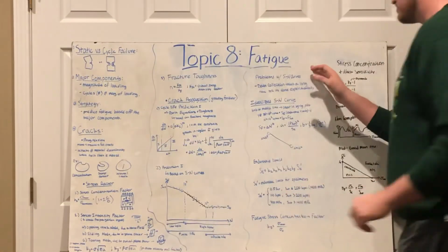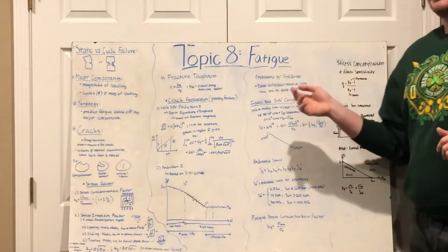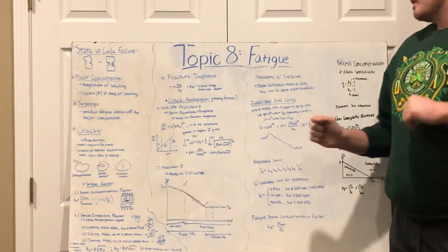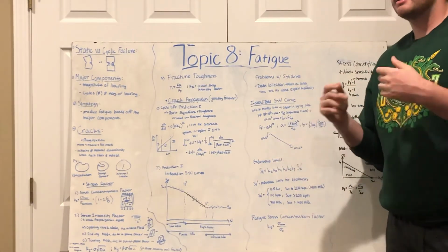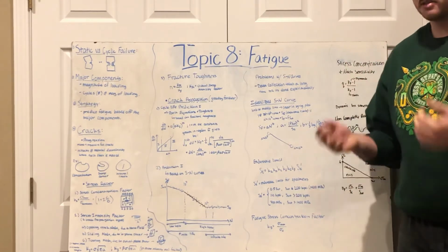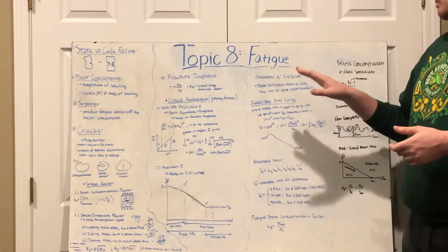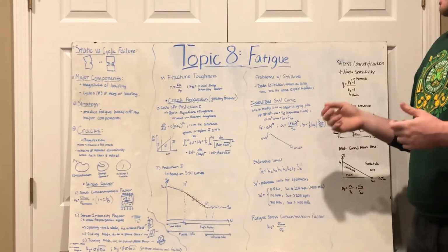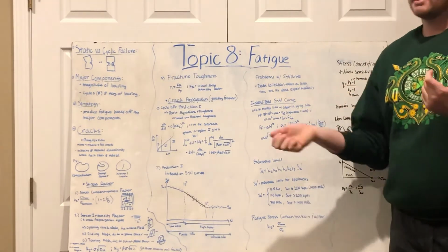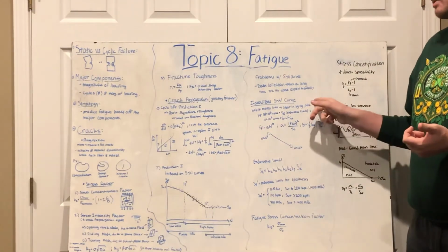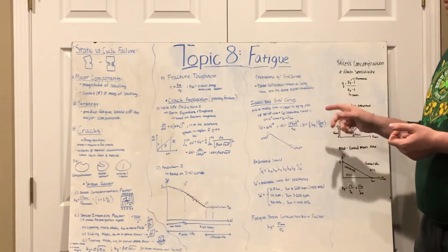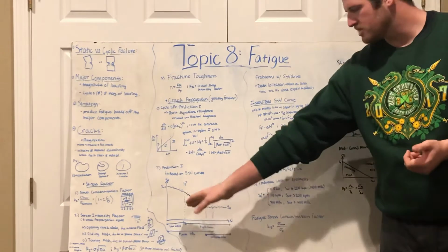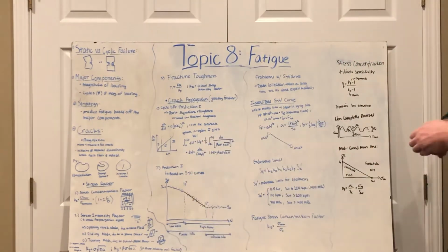Now, let's look at the problems with the SN curves. Like I just said, all of these dots represent data points, and someone had to conduct a test to find each one. That takes a long time because it's done experimentally. So instead of taking all this data, we'll look at an idealized SN curve. We definitely want to focus on this middle region represented by the black line.